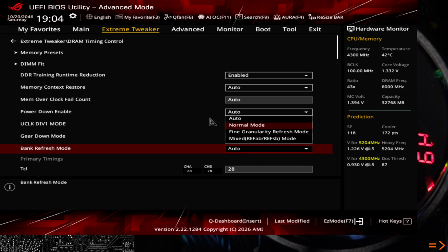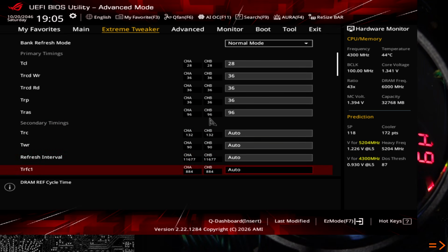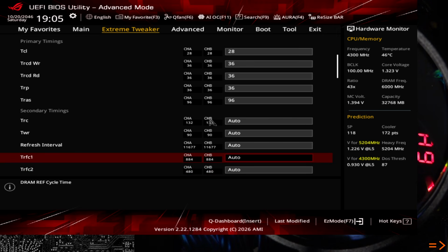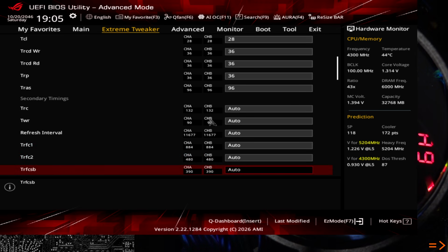But the first thing we're going to look at is how they interact with the memory timings, because that has apparently been causing issues, because apparently some Expo DDR5 kits do not have their tRFC timings set correctly. And so the AGESA update, which I've been told is supposed to be defaulting to FGR mode for default refresh behavior now. Some memory kits don't have their Expo timings or XMP timings set properly to function in FGR mode, and that causes systems to not post.